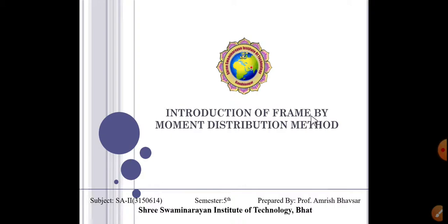We can analyze any beam with the help of the slope deflection method and the moment distribution method. But for frame analysis in particular, the moment distribution method is the most suitable method. So in this lecture we will discuss how we can analyze the frame structure using the moment distribution method.